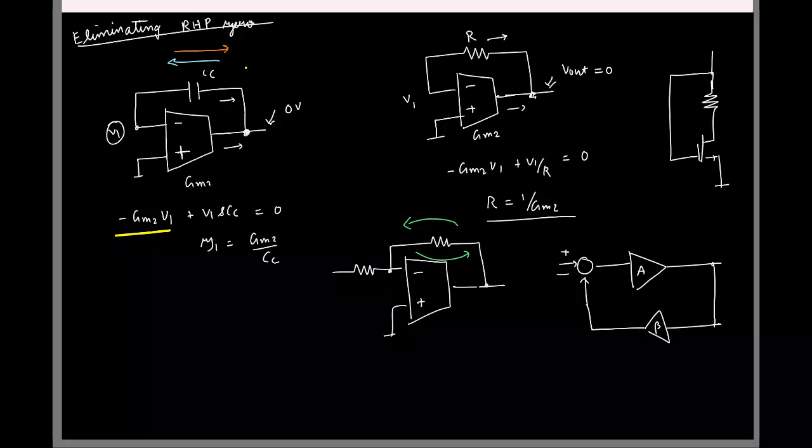This is actually no longer valid because you not only have a feedback, you also have a feed forward. Okay, so to model that feed forward path, you actually have to add some other thing like this. Because the resistor is not only contributing to beta, but it also contributes to some signal transfer in the forward direction. Okay.